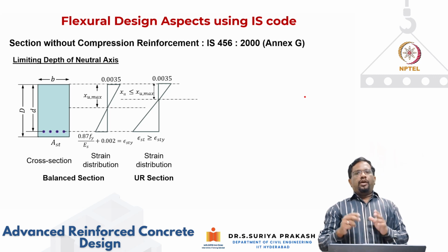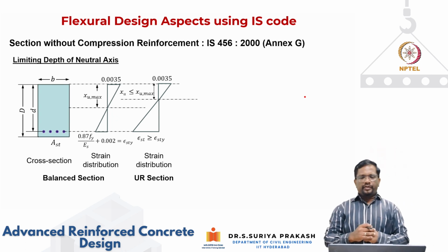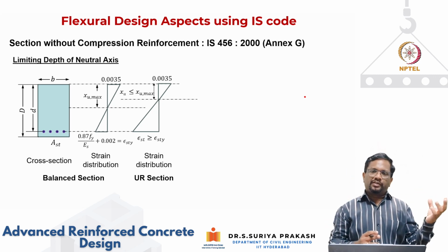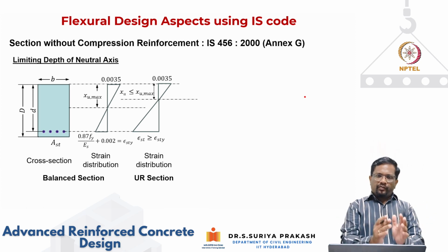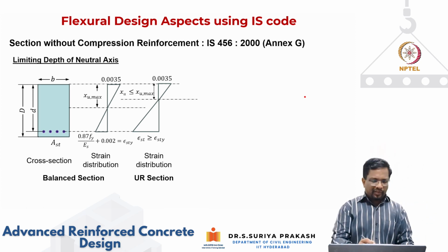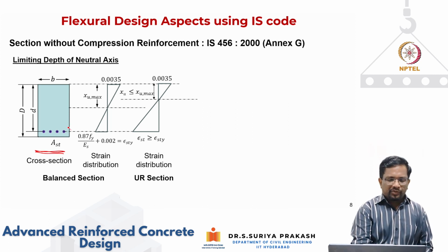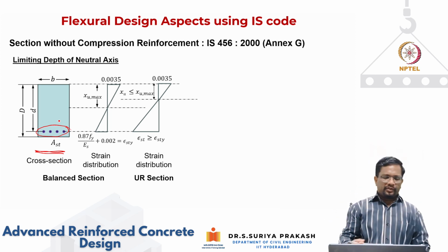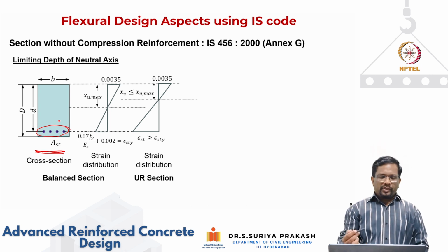Now we are going to start how to analyze the singly reinforced sections. Now that we have seen the design stress strain curve for concrete and the design stress strain curve for steel to be used, let's take a simple singly reinforced section like the one shown here. Again, what is a singly reinforced section? You have reinforcement only on one side, which is the tension side. This is the typical section that we take with B and D as overall depth, and small d is your effective depth.